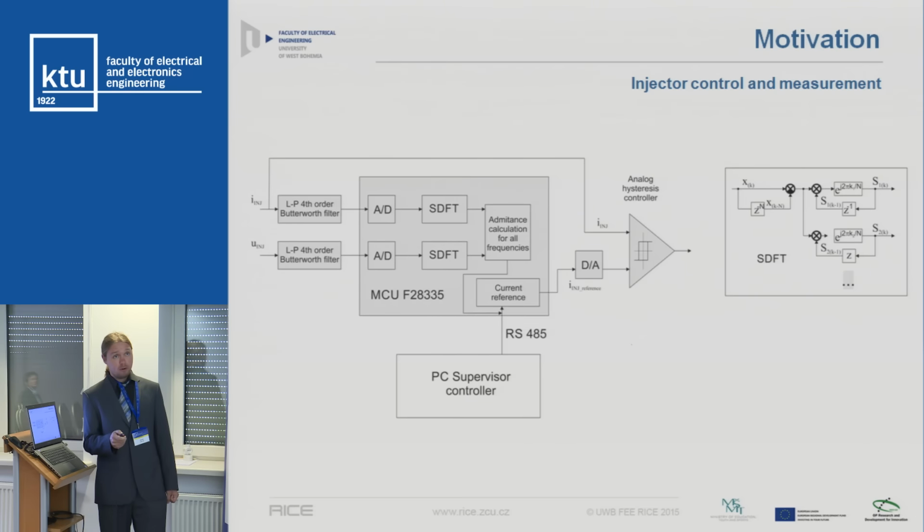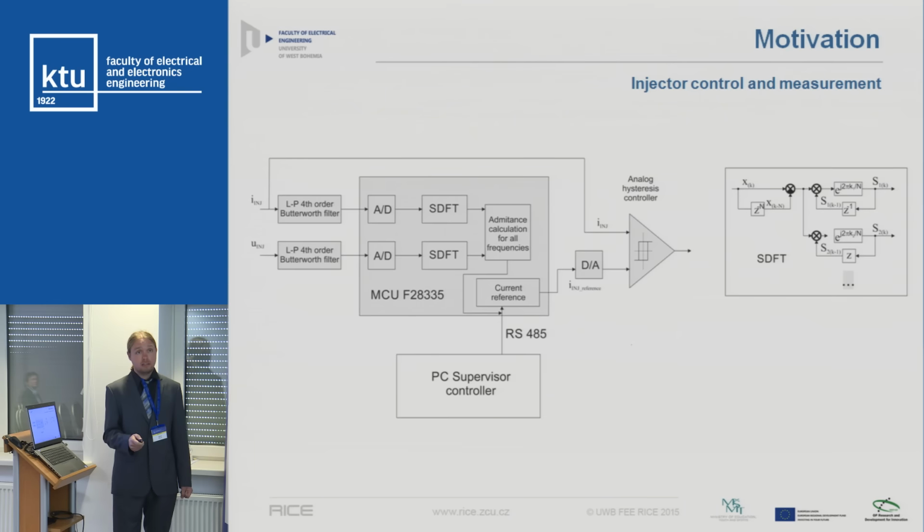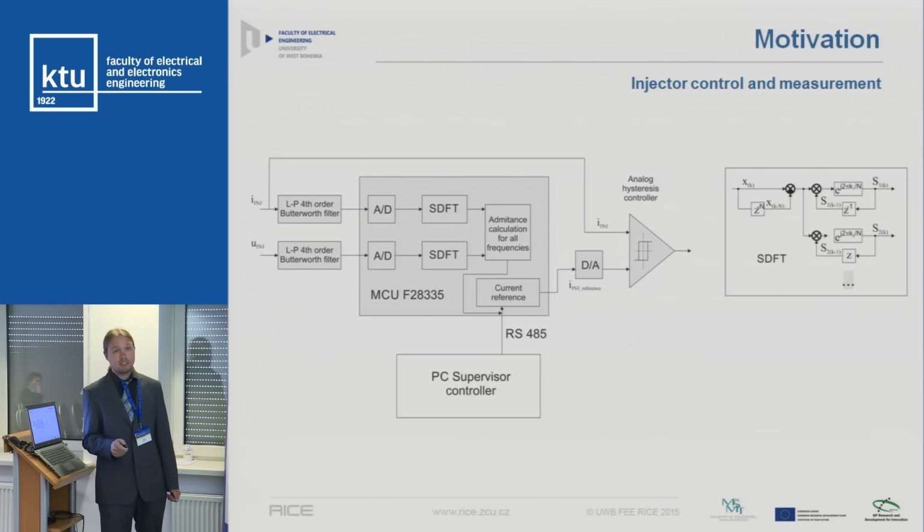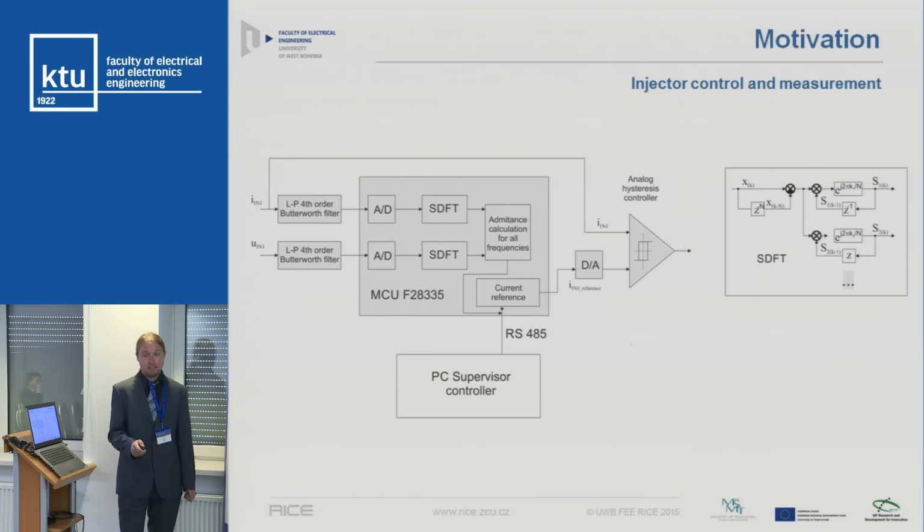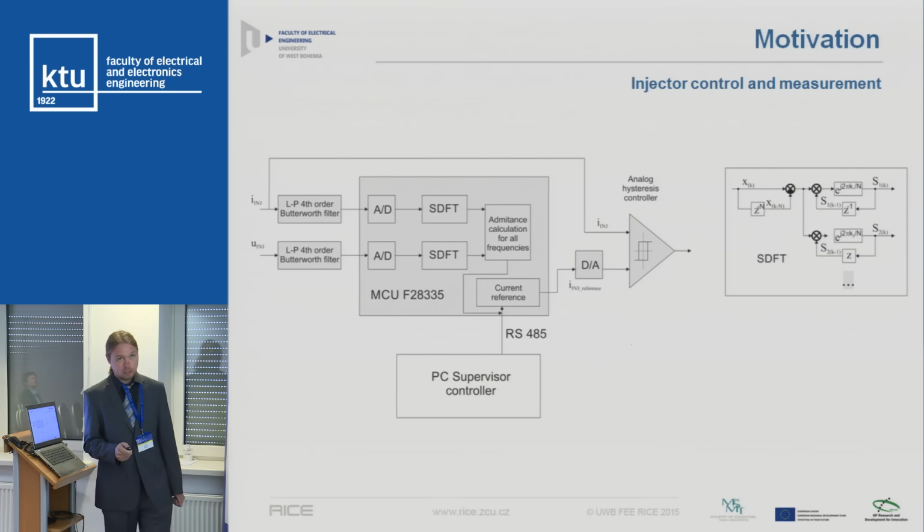As I mentioned before, the current of our injector is controlled by an analog hysteresis controller, and the reference for the analog hysteresis controller was calculated by the processor and set by a digital analog converter to the hysteresis analog controller.